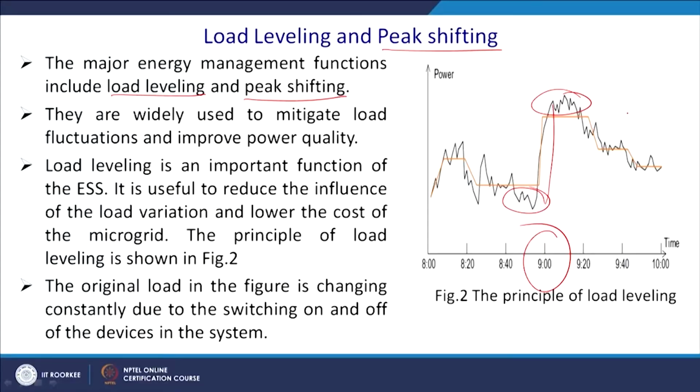Load leveling is an important function of the ESS. It is useful to reduce the influence of load variations and lower the cost of the microgrid, because the difference between the actual generation and the load has to be supported by your energy storage element. The greater the mismatch, the bigger the size of the energy storage element.